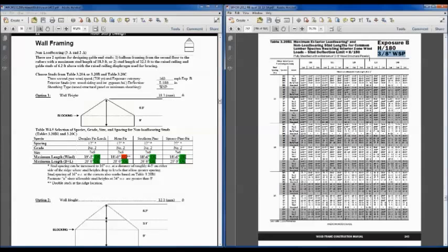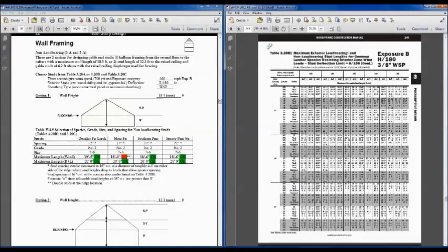And this is actually standardized in the wind and seismic standard, but if you're familiar with repetitive member factor, C sub R, in the NDS, that allows you to take a 15% increase on bending for studs. 15% increase for bending on any kind of bending member. And the studs in this case are in bending due to the lateral wind loads. In the wind and seismic standard, what we allow as high as a 1.5 repetitive member factor for 2x4 studs sheathed with 3/8 inch wood structural panels on one side and 1/2 inch gypsum on the other. And so these tables all have that 15% increase built in for